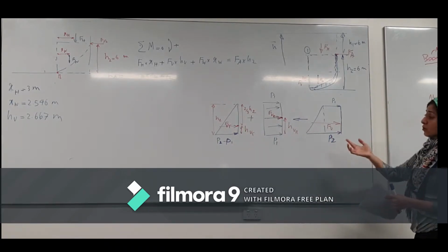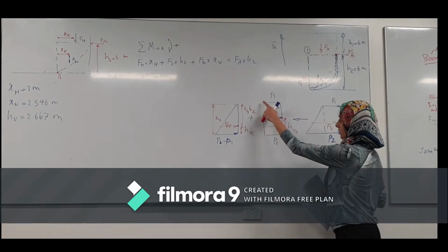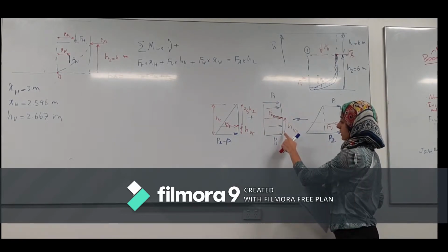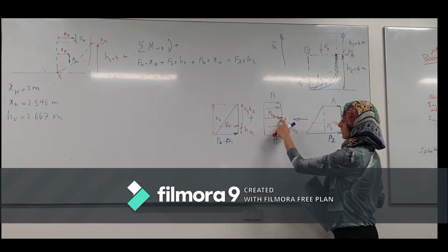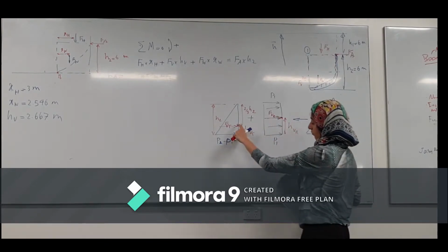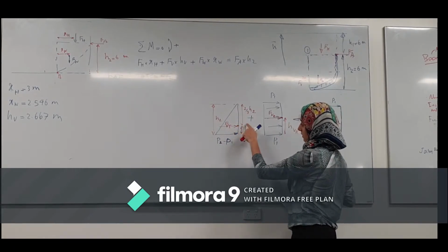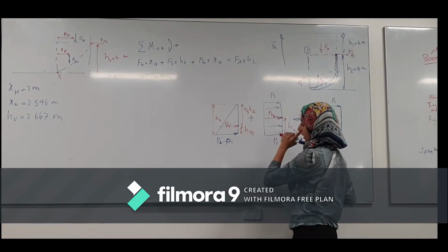We don't need to calculate YP anymore, because for the constant pressure, which has a rectangular shape, we know the center of the pressure is actually at the center, and for the triangle shape, we just learned in the lecture notes, it's about 2/3 of the h.